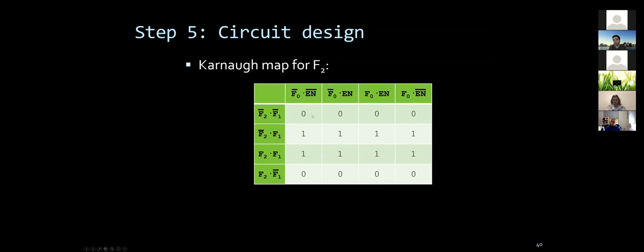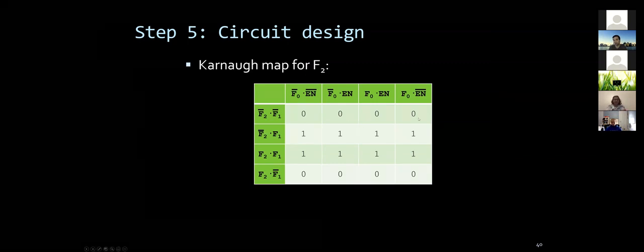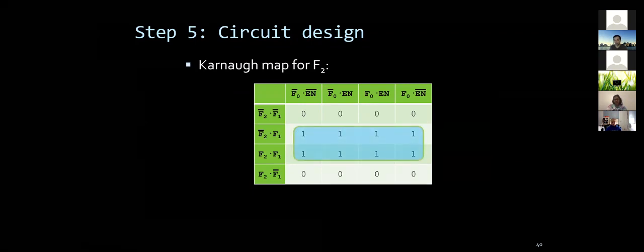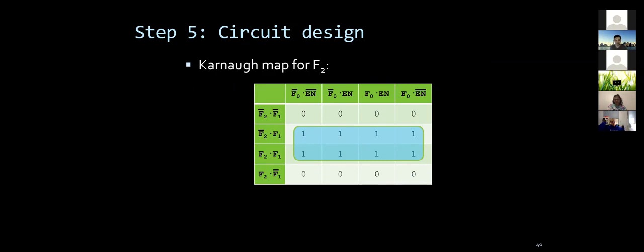And as you can see here, these are the values that define the behavior of this circuit. If we just look at the truth table and the values there, it simplifies your life so you don't need to go back and forth, but you can check me later on. This is the truth table I'm going to get, and that's essentially the K-maps I'm going to get there. It's relatively straightforward to apply K-maps to that. You see all these ones in the middle that form a 4x2 matrix, right?